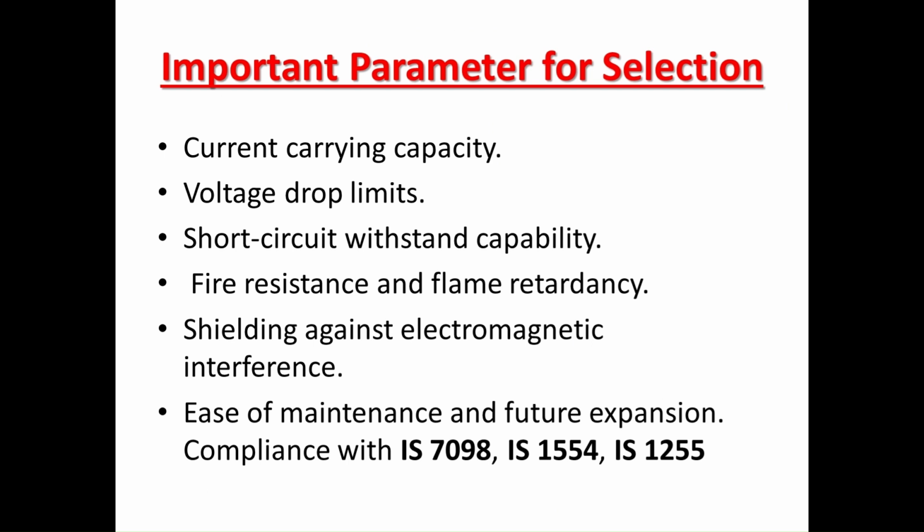So here are the parameters for selecting the proper cable depending on the application: the current carrying capacity, voltage drop limit, short circuit withstand capability, fire resistance, and flame retardancy, because it carries either power or data, and if it is disturbed, it will lead to severe damage. Similarly, shielding against electromagnetic interference, and it should be easy for maintenance and future expansion.